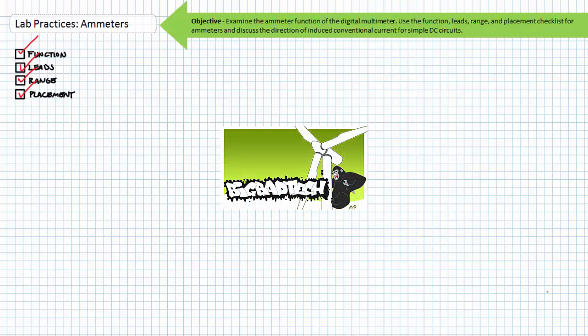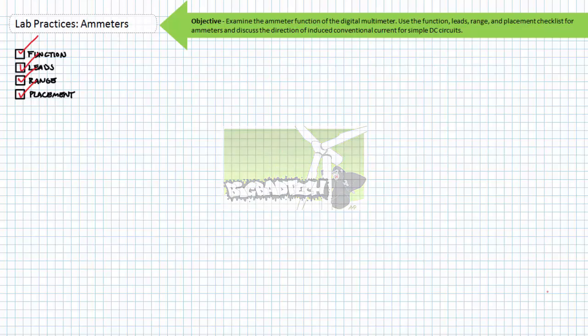Again, understanding the content of the DC Power Supplies lecture, available at the Big Bad Tech channel, we realize this power supply is current limited, and the 5-volt power supply is incapable of supplying current in excess of 0.2 amps or 200 milliamperes, even though it says 2 amps on the front. You would never do what I'm about to do in an industrial setting, nor with a supply that is capable of generating current in excess of your ammeter's maximum safe value.